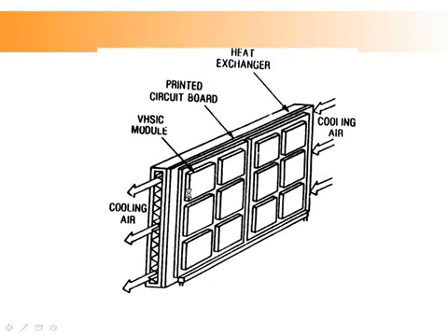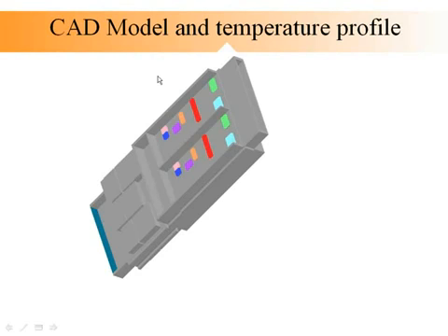And now what we are doing is, we build CAD models of those, and what I'm showing you here is the heat exchanger. Here is the board with all these devices in there, and then we do the finite element analysis, and we also do measurements through mockups using the same heat loading.